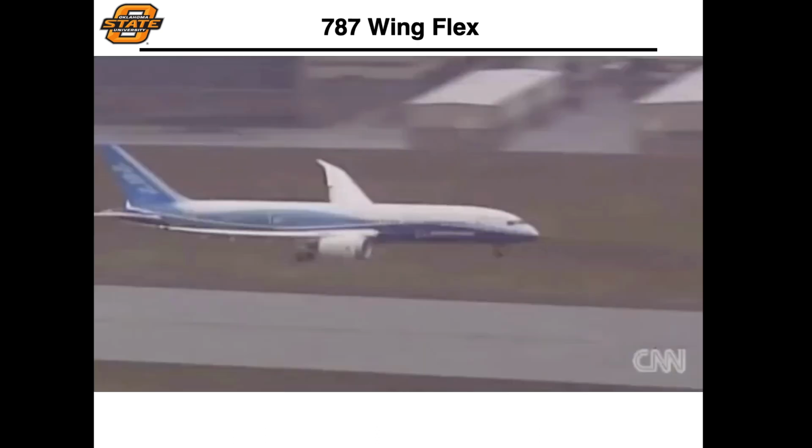Now here's an example of the Boeing 787 coming in on a landing. As it's approaching its landing, again, we can assume that this is a quasi steady state attitude that it's in. Even though it's descending, that's a relatively slow flight, so again, it's more or less in level and steady flight. So we expect lift to be equal to weight in this scenario.